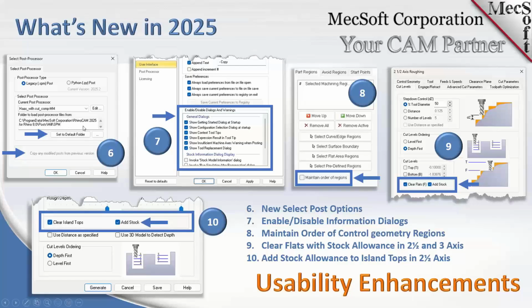So if you've adjusted this folder to load post-processor files from, if you pick this little button here with 3 dots on it and you changed it to where you thought your post was, and then you realize your post isn't there, it's actually in my install path. Now you can just pick this button and it'll automatically change it back to the default location of the folder where to load post-processor files from. So this will be very helpful if you need to use it.